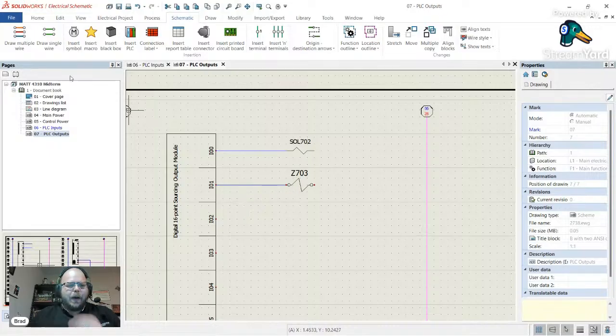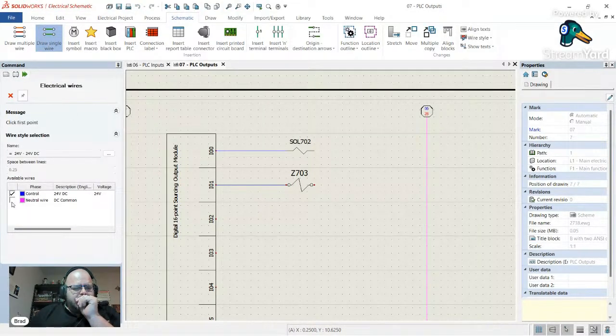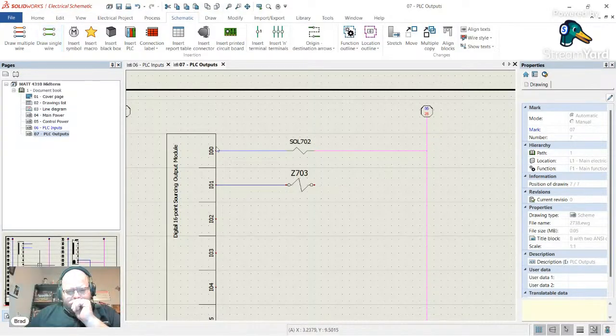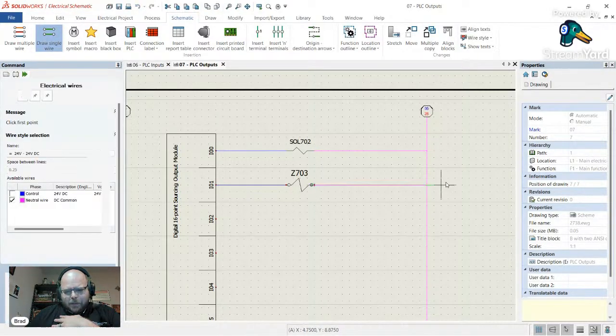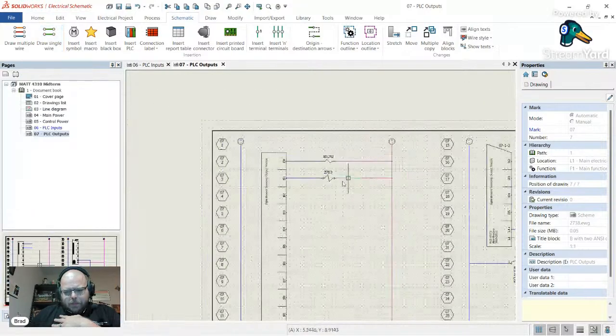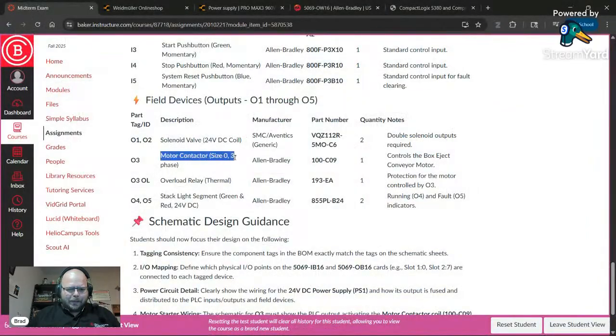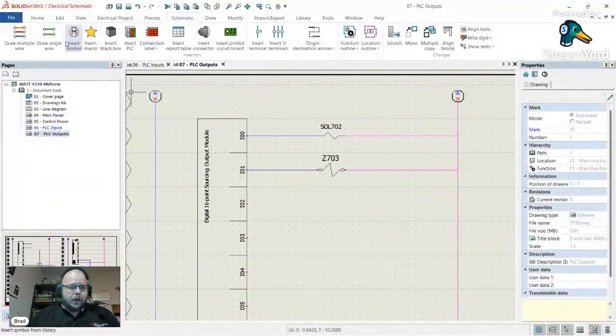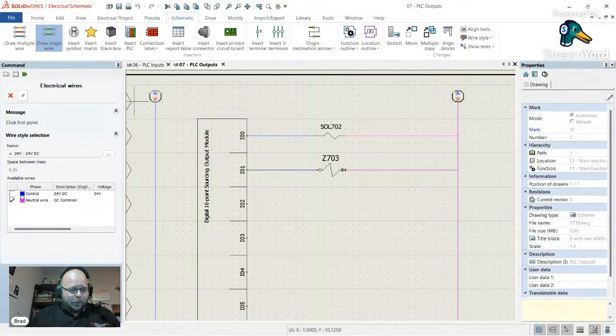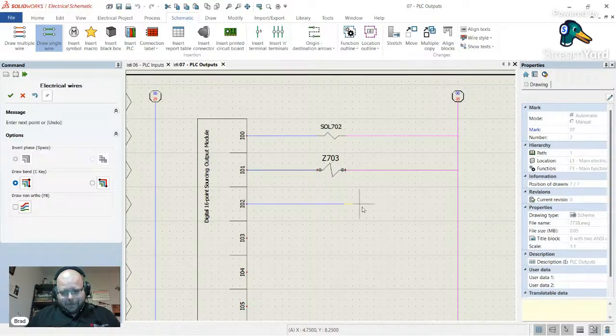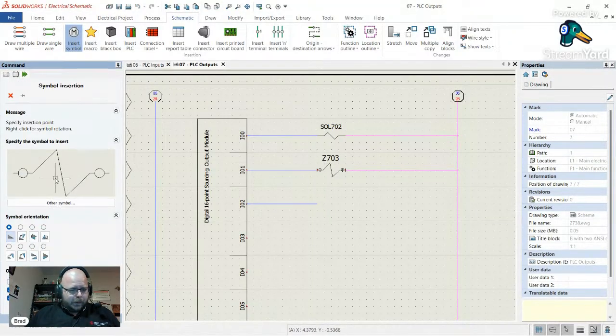But for now, I'm not going to bother giving those part numbers and creating manufacturer parts for those. There's a video on this channel on how to create manufacturer parts or even import them. I'm not going to go through that right now. But what I am going to do is, I don't have to do things in order, but I wanted to get the motor contactor coil in there. That's really why I just went through all that. I wanted to get those populated.